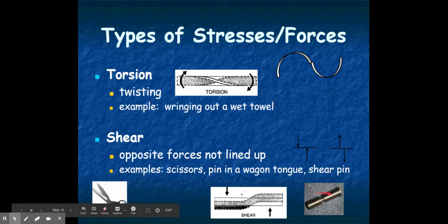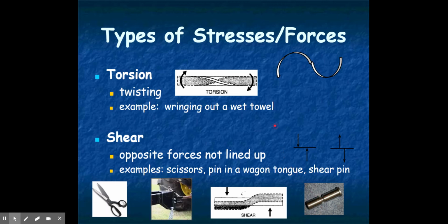And here is what's called a shear pin. And this is designed to give. So right in here is a certain amount of shear force that's going to break this. And it's designed as a safety device, because in case there's something you don't want to get overstressed or have too much force buildup in it, then this will shear before it gets to that point and let go.